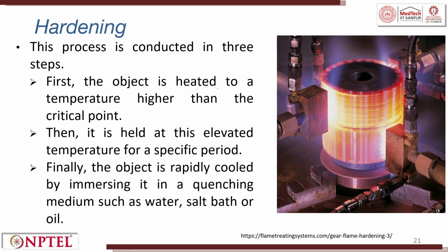First, the object is heated to a temperature higher than the critical point. Then, it is held at the elevated temperature for a specific period. Finally, the object is rapidly cooled by immersing it in a quenching medium like water, salt bath and oil. You can also have air cooling.